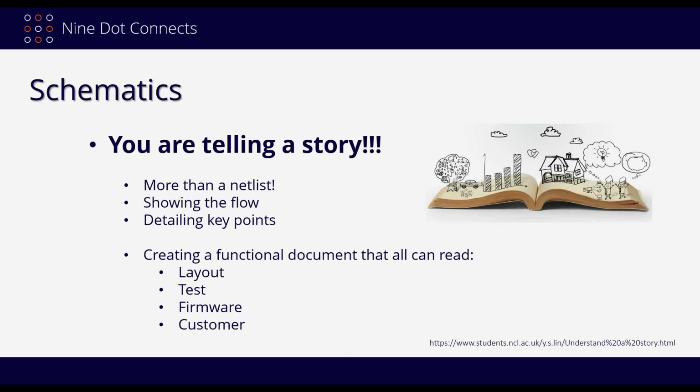Because if you go to the ASIC side of things, they've given up on schematics. They don't do schematics anymore. They do everything in code, and that code is synthesized into a net list. And yeah, their placement tools will show you graphically what's going on, but on the ASIC side of things, they don't do that. So why are we doing it? Well, because we're manufacturing more than just a chip. We're manufacturing a whole functional system that has a number of components on it.